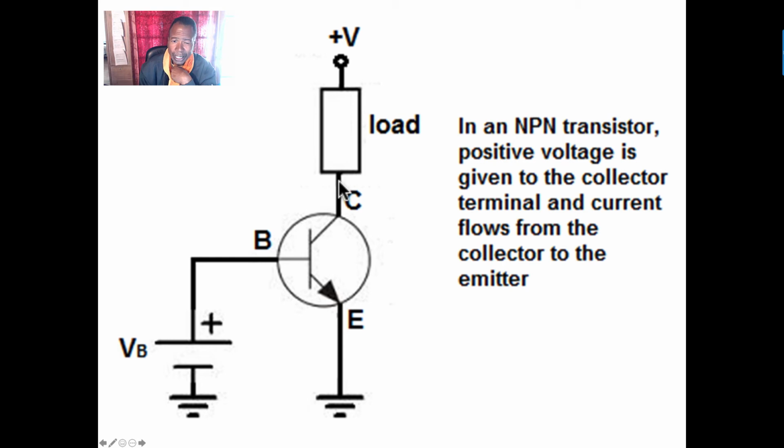The module has the collector, the little transistor. This right here, it's your set of points. So go through the collector, through the base, through the emitter to ground. When the emitter is closed, like a set of points, we're charging up the coil, primary side of the coil, primary side of the windings.